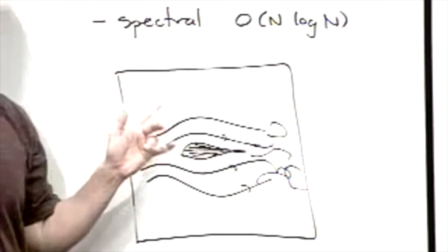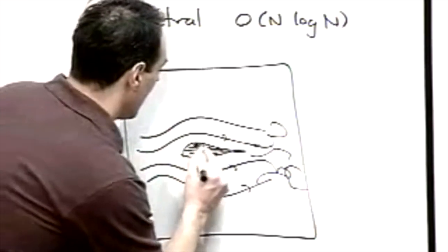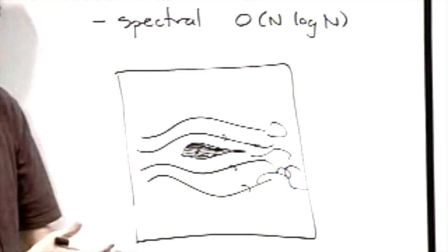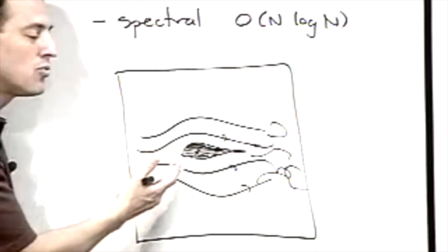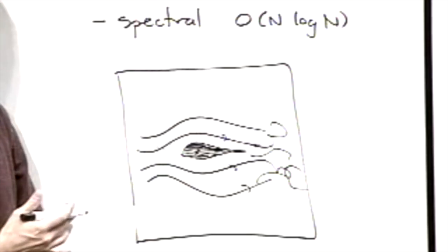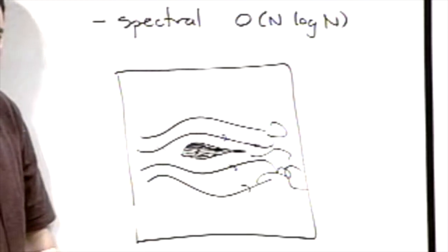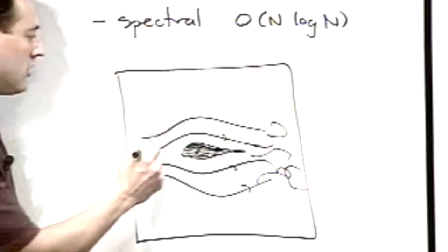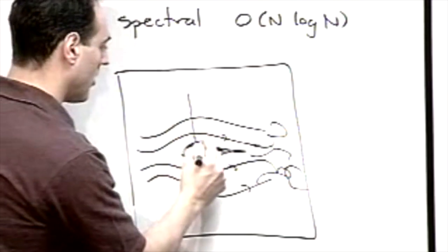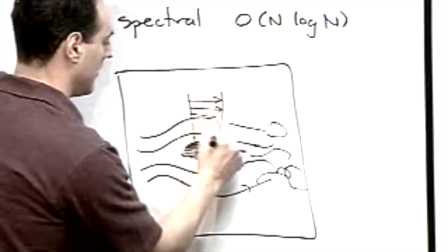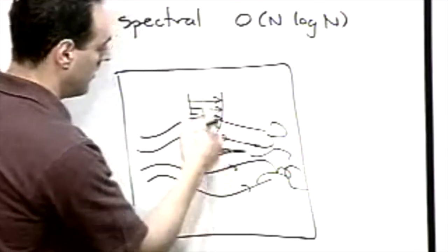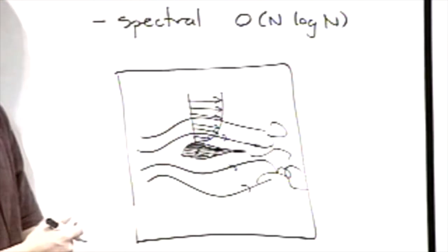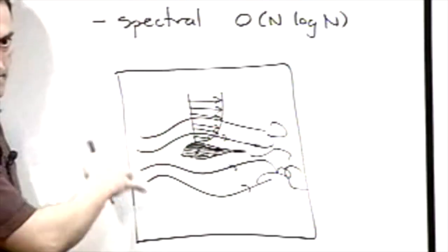But when you go to a problem like this, here's what's interesting. This wing, you're pretty much assuming there's no fluid flow inside of this wing, right? So this wing in your computational domain represents the boundary condition. In particular, when you go to the wing, there's typically what's called a no-slip boundary condition. That's the idealization. So your velocity profile across this wing does something like this. And typically this region of transition is called a boundary layer. And you kind of want to know what happens over the wing with the airflow.